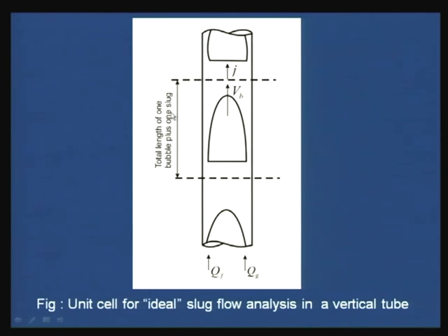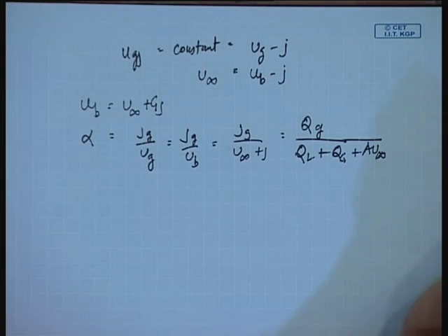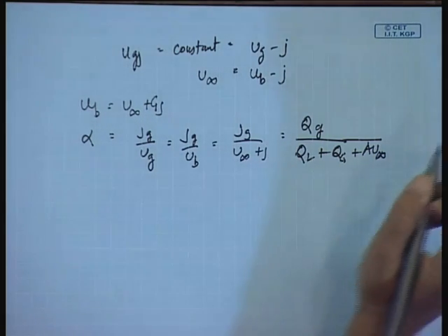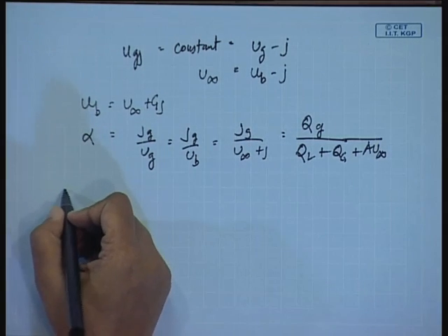So, therefore, depending upon the velocity profile, what we would like to do? We would like to introduce a particular correction, say C1 j, where C1 is a measure of the fact that the bubble does not simply move relative to the average liquid velocity, but a weighted average velocity. You remember when we were doing the drift flux model, how I had introduced the term C0? I do not know whether you remember it.